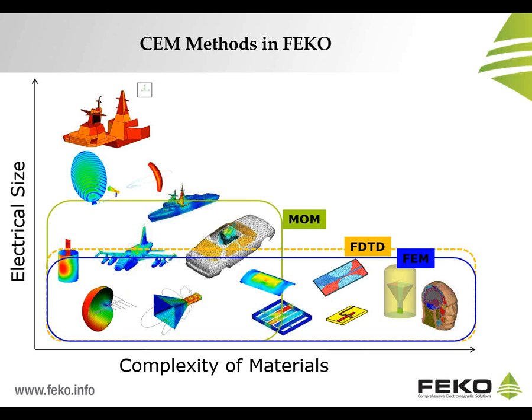The next method to consider is then the method of moments. Now, whereas the finite difference time domain and finite element methods are based on the differential form of Maxwell's equations, the method of moments is based on the integral equation format of Maxwell's equations. In computational electromagnetics, that means that we only have to mesh the surface of the problem that we are solving, and as such we achieve a much more efficient mesh structure than you would for volumetric mesh solvers.